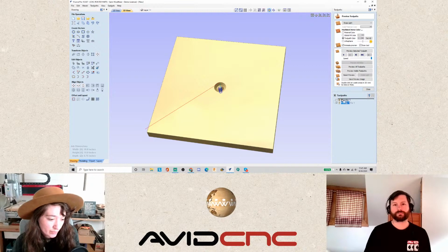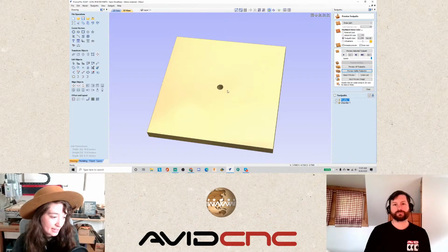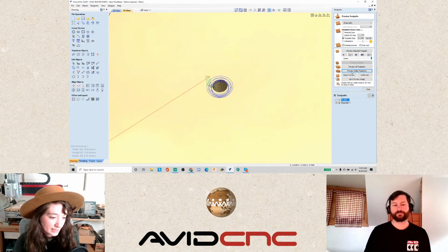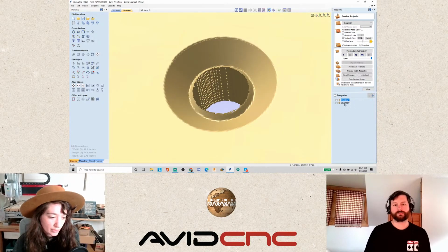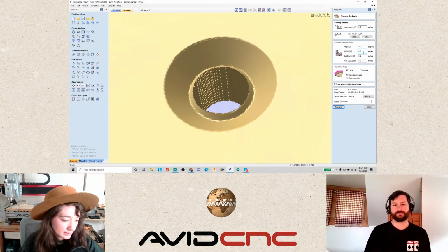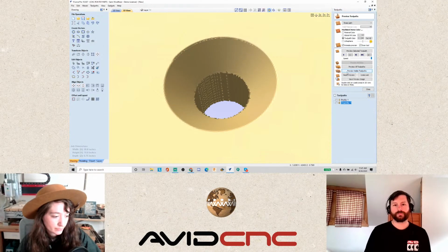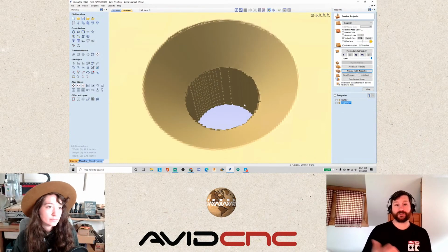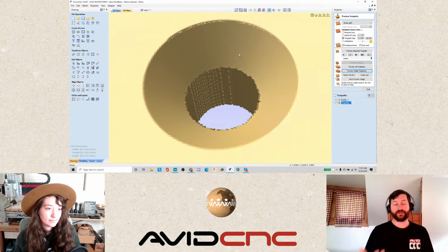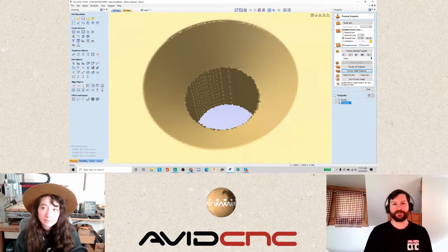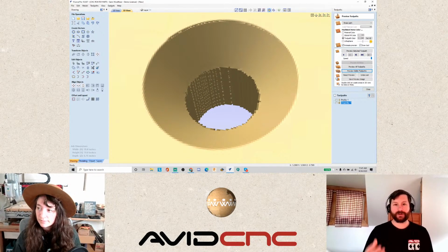And I'm going to run this before my chamfer toolpath, because then if I run that, it will clear out all the space I need for my chamfer here. And I would maybe make an adjustment here so this is meeting up better. Yeah, and this is a great thing about the Vectric preview with your toolpaths, is you get an instant visual feedback there. And that's so powerful when we talk about correcting mistakes before they're on the finished part.